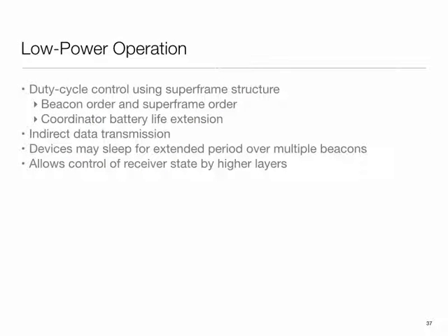So what happens is that there is this superframe, as it is called, which is that period in which the coordinator of the network, kind of a master node, advertises what the schedule is. Essentially it is controlling how often the nodes get to sleep, and it describes in what order the data for each node would occur. The node gets all this information, and then it can go to sleep and just wake up at the time when there is data for it. So devices in this case can sleep for long periods of time.